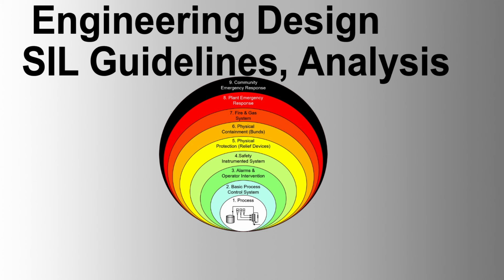Disadvantages. 1. Static nature. FTA is generally static and does not explicitly account for time-dependent factors such as maintenance and repair activities. 2. Complex fault trees. For large and complex systems, the fault trees can become very large and difficult to manage, potentially obscuring critical failure paths. 3. Assumptions on independence. FTA often assumes the independence of component failures, which may not always be realistic, especially in systems with common cause failures. 4. Limited dynamic modeling. It is less effective in modeling dynamic aspects such as changes in failure rates over time or the impact of different maintenance strategies.